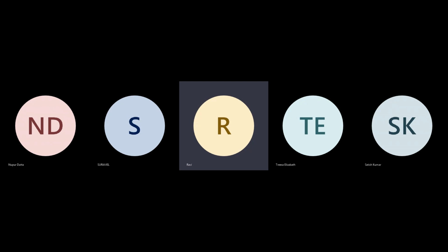Put all the blockages necessary. Macros, everything. Let the cells not go and sit in the corners. Don't think there are DRCs here, I'll fix it later. Then when you start removing it, it will create mess. So create as many constraints as needed, but simplify the design and run it as a quick shot.